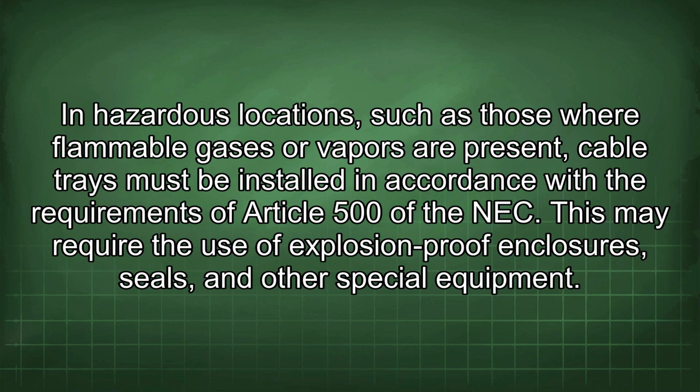In hazardous locations, such as those where flammable gases or vapors are present, cable trays must be installed in accordance with the requirements of Article 500 of the NEC. This may require the use of explosion-proof enclosures, seals, and other special equipment.